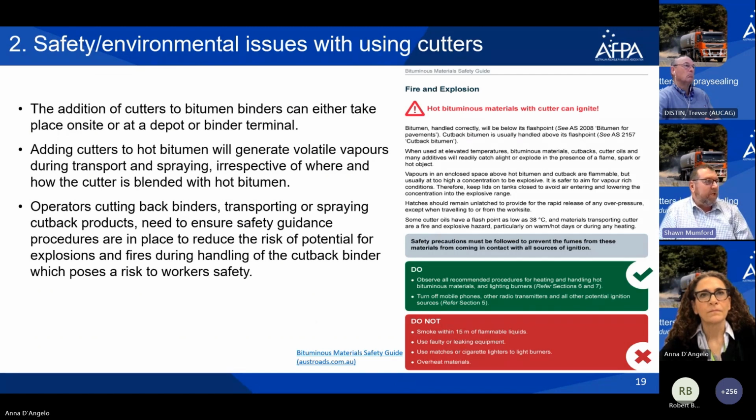So in using cutters, there's obviously some safety concerns and issues that will crop up from time to time. The cutters added to the bitumen normally take place on site or at a depot or at a binder terminal, and are obviously circulated in those bitumens or binders before spraying takes place to reduce the viscosity.